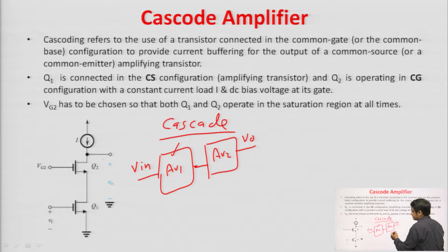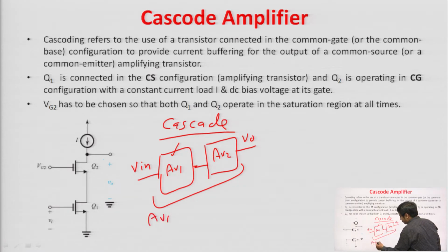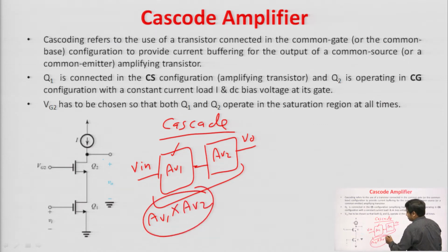This is your cascade structure, this is also called 2 stage amplifier. So, we can design 3 stage amplifier, 4 stage amplifier, n stage amplifier and the gain of this overall structure is the multiplication of the voltage gain of the individual stages. So, in cascade, we do the cascading of the amplifier stages to increase the gain. This is about the cascade, this is called multi-stage amplifier, fine.